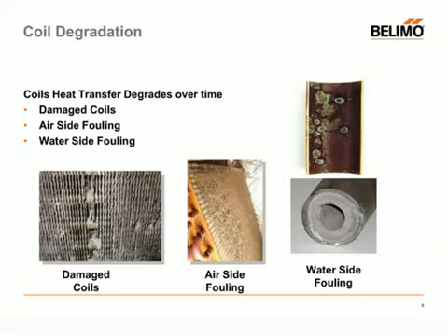When we talk about damage, we can talk about pure deterioration or rust of the metal, the fins breaking down, changing that geometry, and again, changing the heat transfer and performance of the coil. Another thing that could happen is when a coil is serviced. Perhaps a service technician whacks it with an elbow or a wrench, bending those fins over, and that would also impede the heat transfer because it causes changes to that specific geometry. So that's what we talk about when we talk about damaged coils.